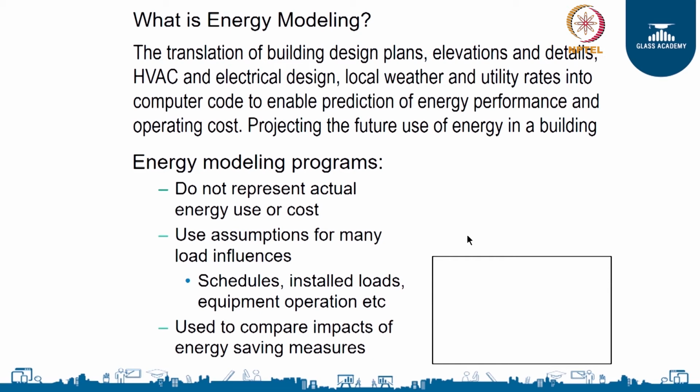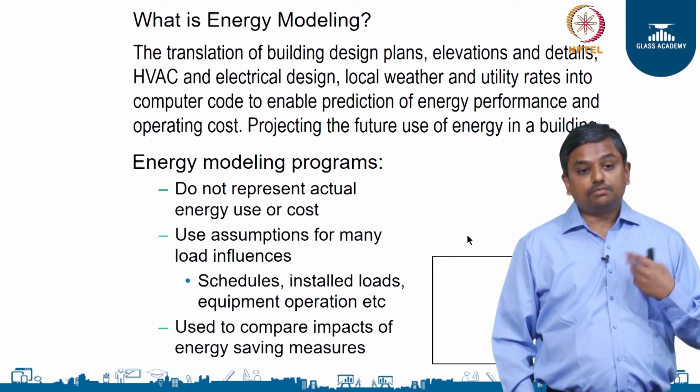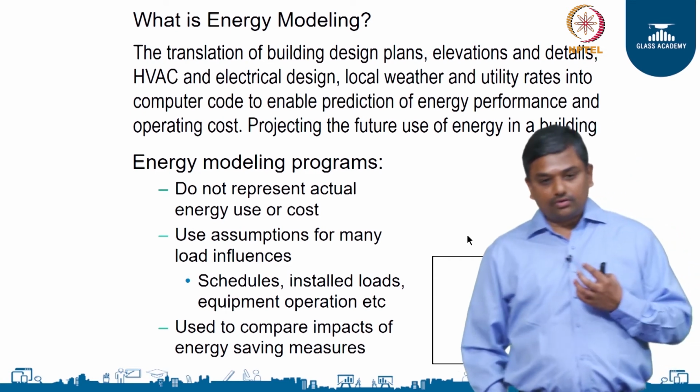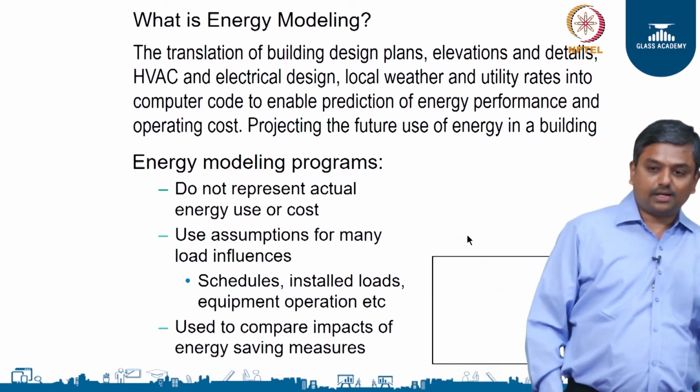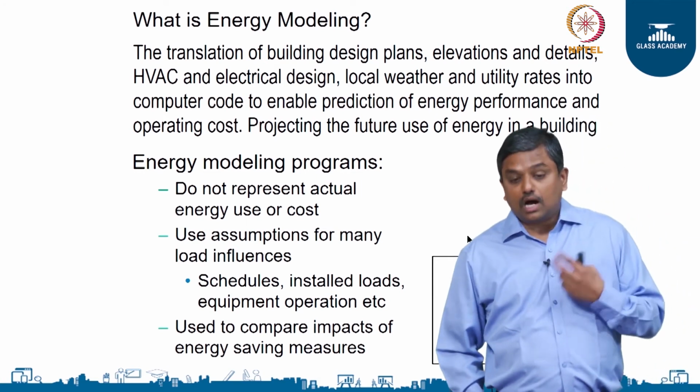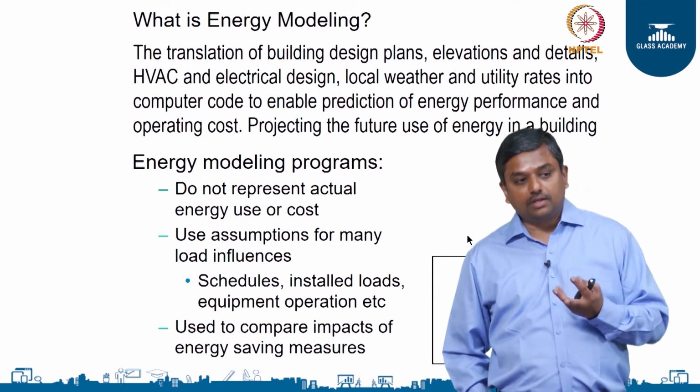And then what we do is we use very intensive weather data that is available today from most of these organizations, which include ASHRAE and ISHRAE, and we feed the hourly weather data of that particular location into the software. And then it helps you to predict the energy performance of the building, given all these inputs, for 8,760 hours throughout the year, right. So, we are basically doing an hourly simulation of energy performance of the building throughout the year.